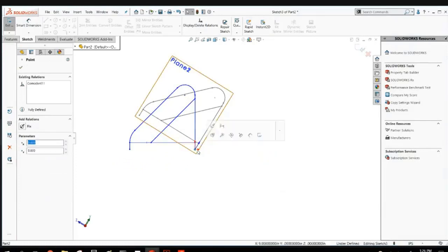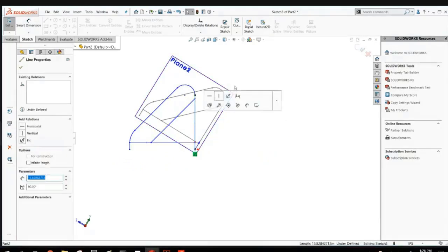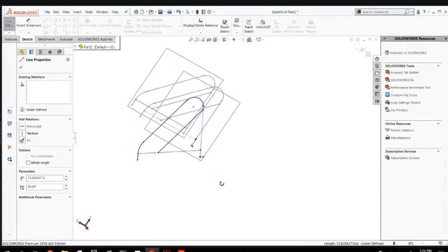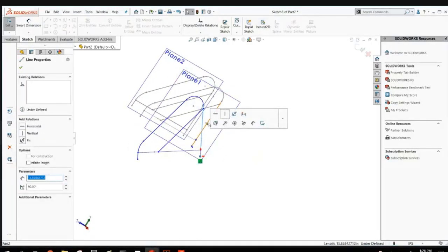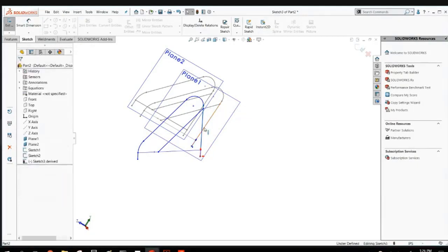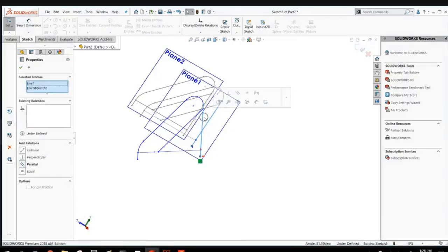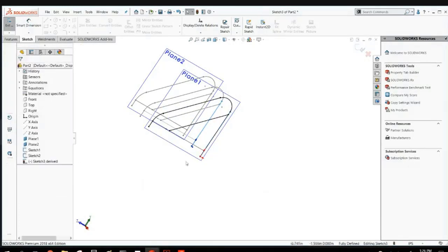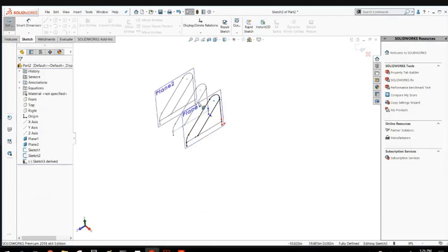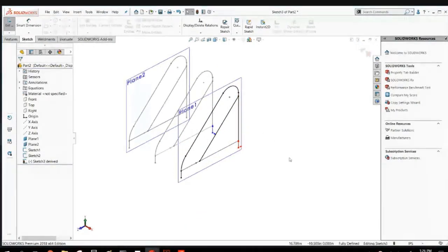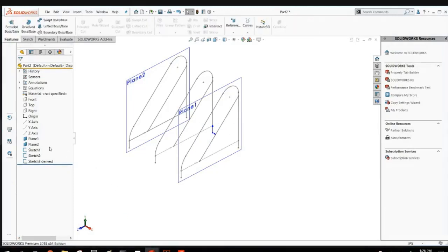You see with the derived sketch, if I do locate it, and I give it an orientation, I actually want it oriented parallel to these originals. There we go. You see that it turns fully defined without a single dimension because it is the same size and shape of the original sketch. All I'm doing is giving it a location. There you go, a little bit about copying sketches.